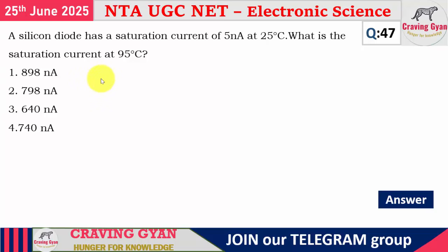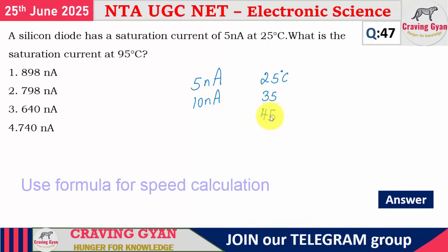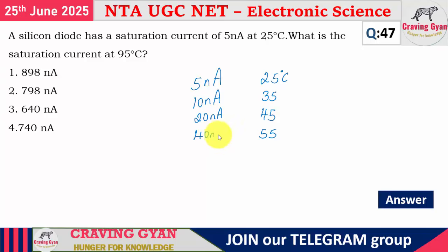A silicon diode has a saturation current of 5 nanoampere at 25 degrees centigrade. What is the saturation current at 95 degrees centigrade? Now look at things. For every 10 degree rise in temperature, the reverse current will get doubled. At 35 degrees centigrade, what happens to the current? 10 nanoamperes will be the current flowing. At 45 degrees centigrade, 20 nanoamperes. At 55 degrees centigrade, it doubles to 40 nanoamperes.